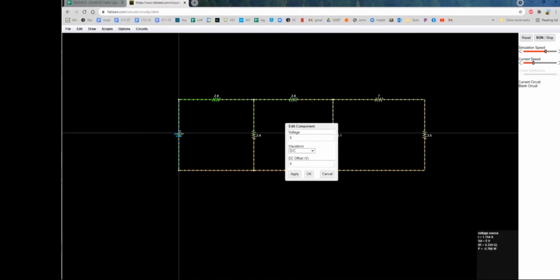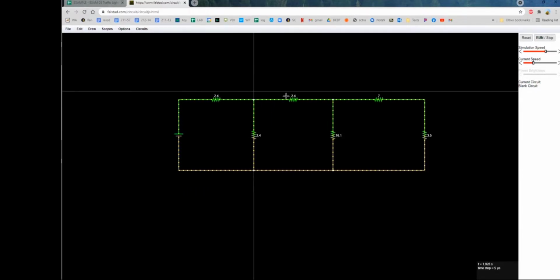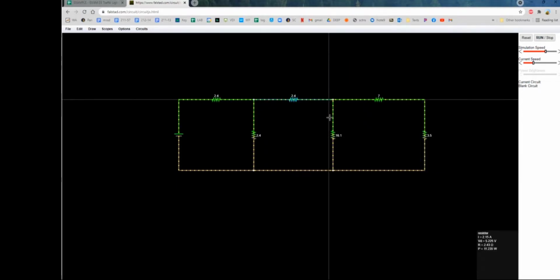Double click on your battery, and let's change this. Ready? 43.05331118. Let's drag along all those digits. I'm just looking at my calculator. My calculator says 43.05331118. Okay, and then say okay. That's it. So we have the voltage value set and the resistances set. Let me know if I need to repeat anything or if you can't see something, because again, this is showing 2.4, but in reality, it's 2.43.